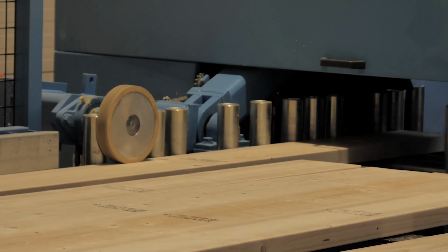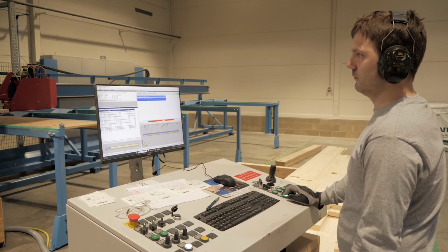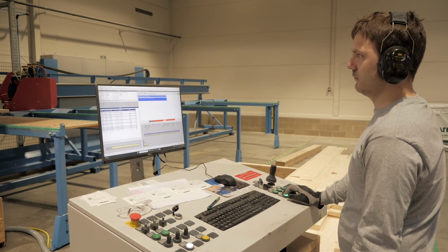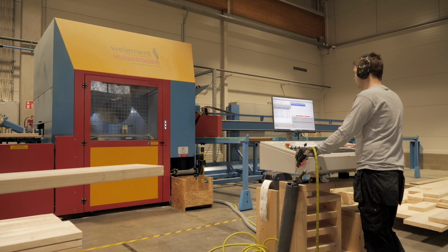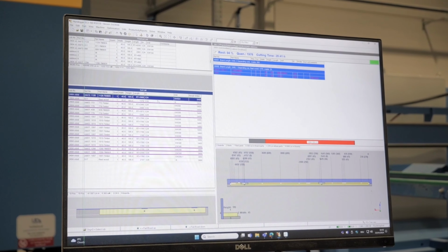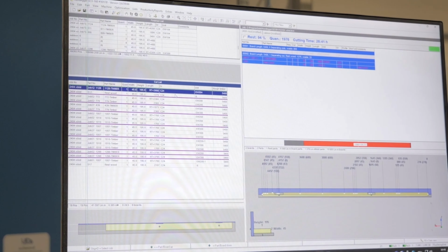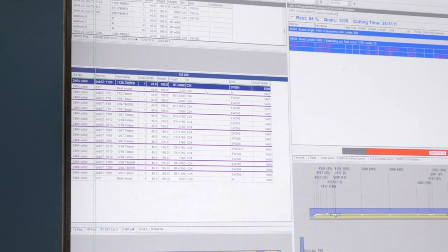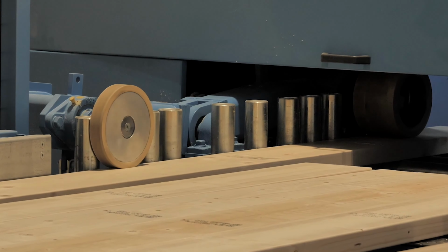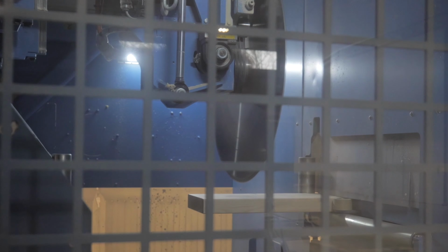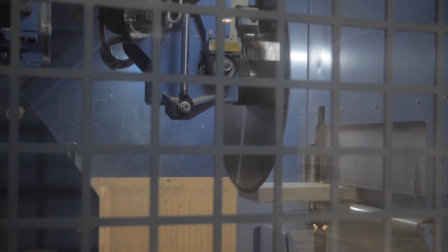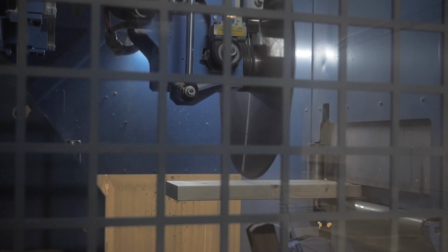If an automatic machine tool is used, then the operator of the machine tool, trained for this purpose, is responsible for cutting the right amount and dimensions of the right parts. Each detail needs to be cut in given measurement ranges, with tolerances that shouldn't be exceeded. In case of any deviation, it should be replaced.